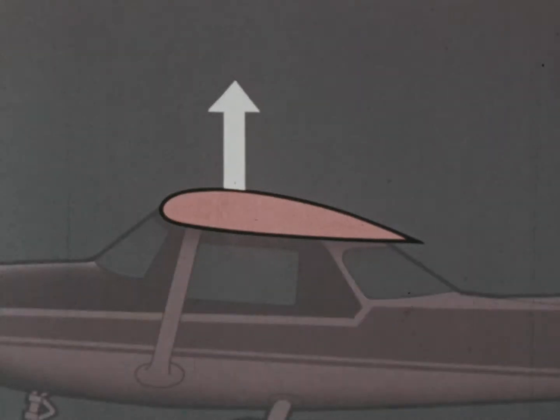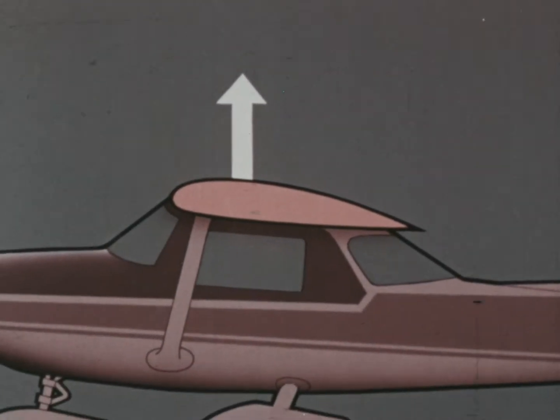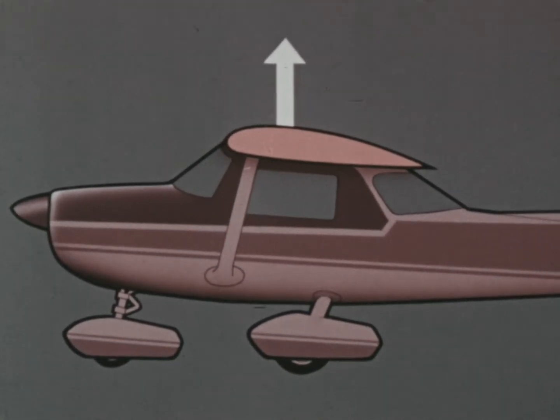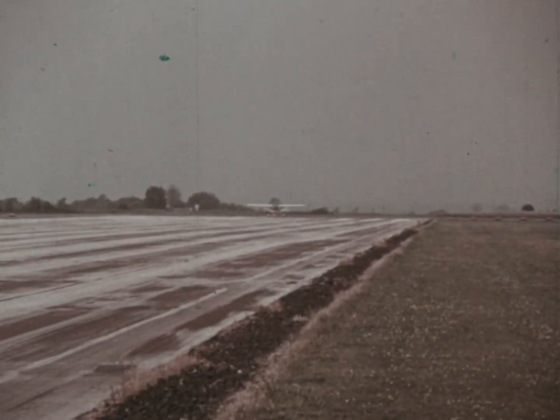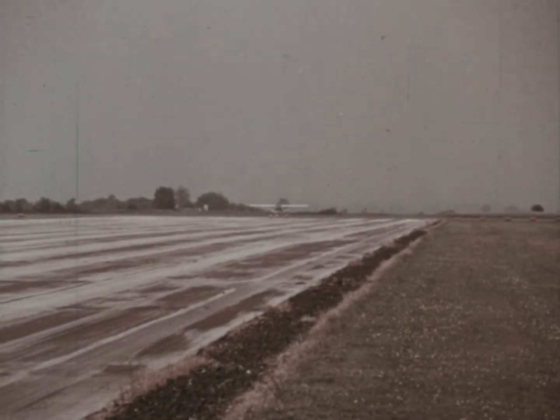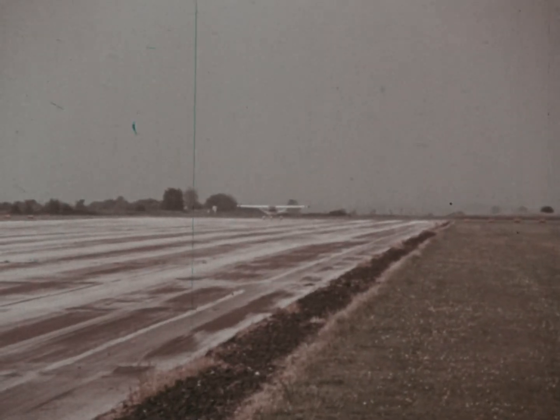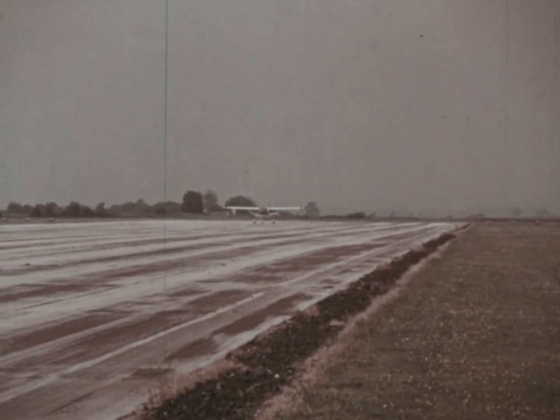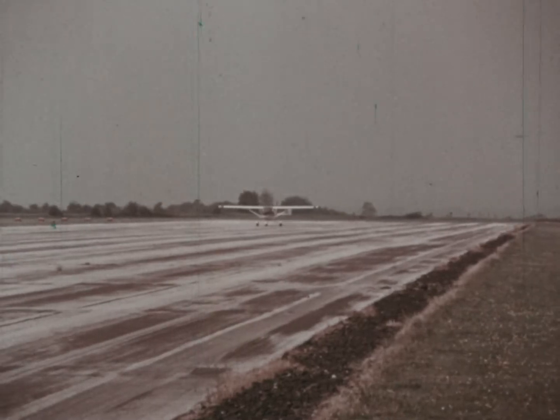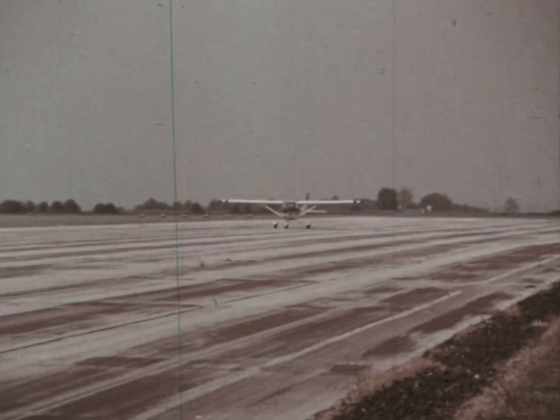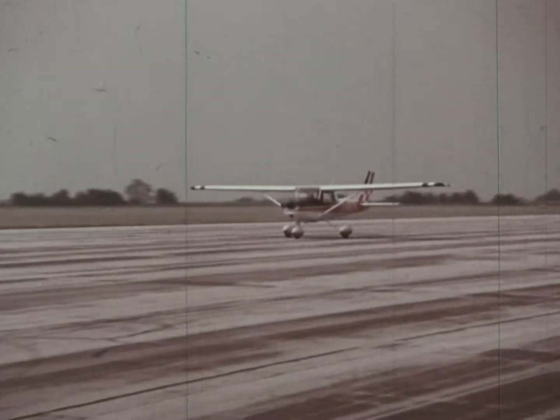And so we have a cambered wing flying at a small angle to the horizontal, producing a resultant lift force exactly equal to the weight of the airplane in steady level flight. Lift increases with speed. We prove it every time we take off. It also increases with an increase in the angle of attack.